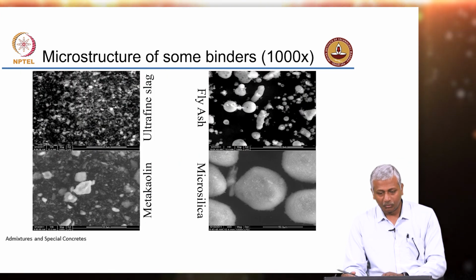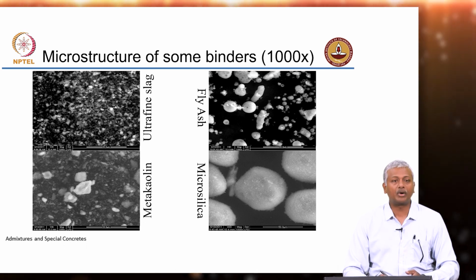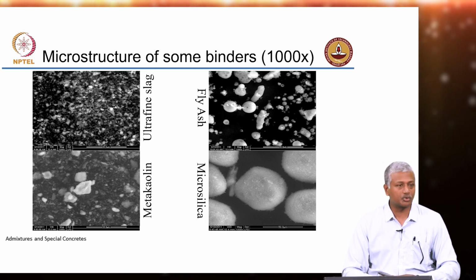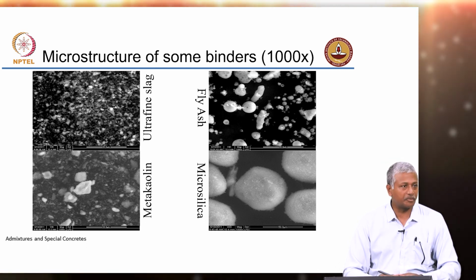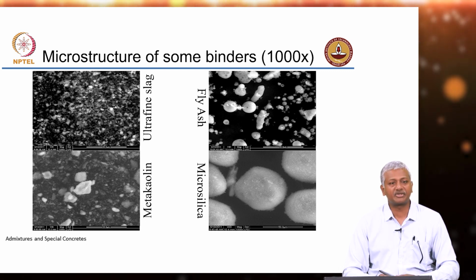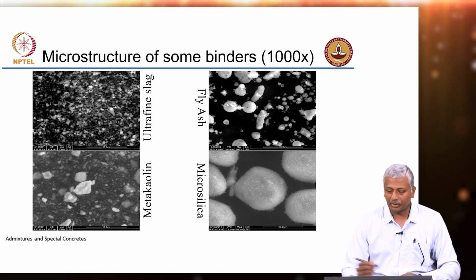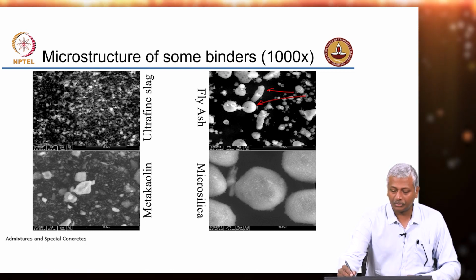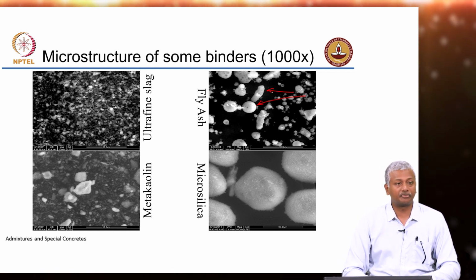So, moving on, one additional scheme of characterization that is typically followed with most mineral additives is microscopy, and under the microscope we can get to see some of these structures more closely. If you look at fly ash, they have mostly these spherical or oblong type of particles.